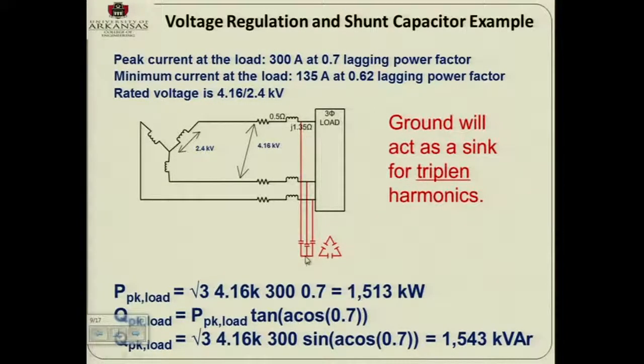So don't think that placing a capacitor is as trivial as the example shown. The initial calculations are like that. The only thing is, how do you design a harmonic filter? You calculate the capacitor as you need for power factor correction.